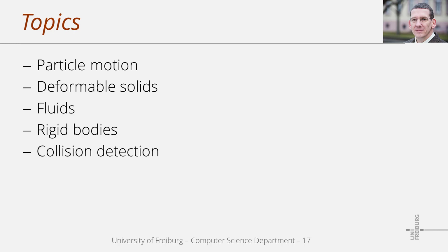In the following, we will see how to compute the forces at the particles. The forces depend on the material that we consider, and in the course we start with elastic solids. If an elastic object is sheared or compressed, then we induce forces that try to preserve the original size and shape of the elastic solid. Next, we look into fluids, and we will see that the force computation for fluid particles is not too different from the force computation at deformable particles. We compute forces that preserve the volume of fluid particles, but in contrast to deformable particles, we do not compute shear forces.